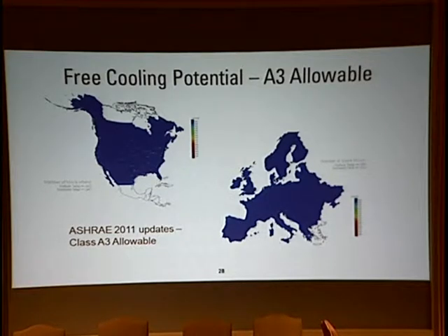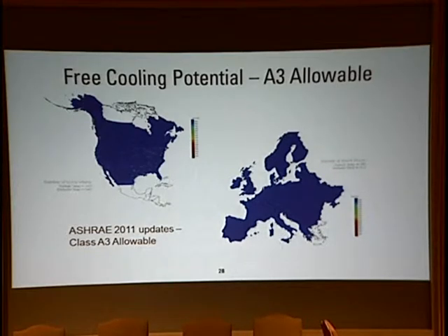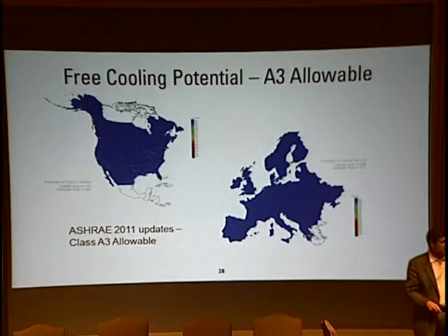This is up to, I think, 5 to 40 degrees C for the dry bulb temperature, and 24 degrees C is the cutoff for the dew point. But you can get some equipment like this, and more manufacturers are starting to do this. Dell announced that they have a couple of servers in their line that allow you to do this. You can buy those servers, you can put a data center in Miami or down in Houston and open the windows and let it run all year long.